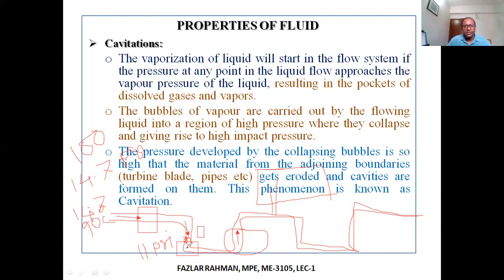So you have a mixture of liquid and some bubbles, and they're flowing along this direction with this mixture. And gradually, every time fluid comes over here, some portion of fluid boils or makes bubbles. That bubble travels with the liquid and comes to this portion. And certainly over here, pressure is high. Then what will happen? Pressure is high, there will be no bubble.